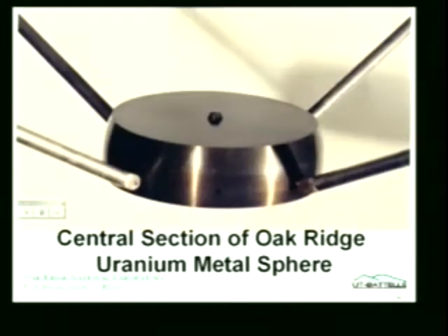This is the central section, mounted on 4 lightweight supports that were pinned to a uranium plug in the system, and these things could move in that direction, so the centerpiece could wobble. What you did is you put a level on here and adjusted this till it was level by adjusting the length of these various arms. There's a little alignment cone which assured that the top piece came down in the right spot.